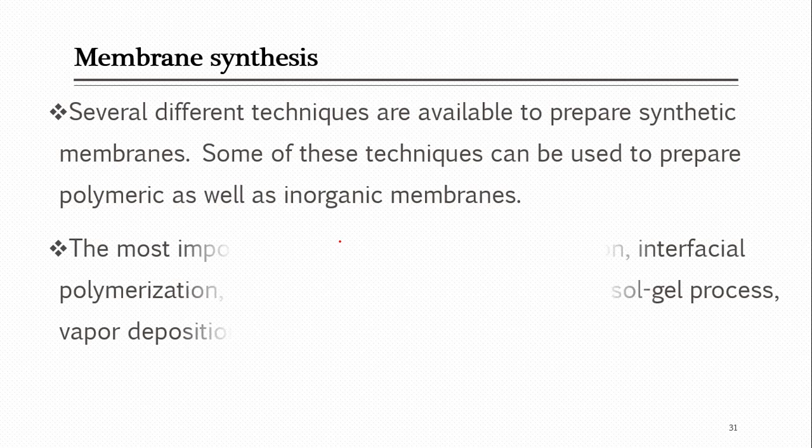So that's it. Up to here we have talked about membrane modules. Briefly summarizing, membrane modules are the arrangement of large surface area membranes for industrial application, and there are different module types. They are flat plate, tubular, hollow fiber, as well as spiral wound modules. We have talked briefly about each type, we didn't go into much detail. We just talked about how they are formed or arranged, how they look, and which special applications they are usually used for.